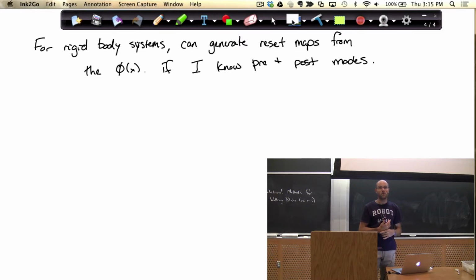But inelastic constraints we end up having to solve with optimization. The closed chains, it's using the same math. You have a kinematic constraint. You have some force that's being applied at the joints to keep that constraint active. But in the case of a closed kinematic chain, you can solve it away. So if you're interested, there's a simple 4-bar example sitting in your Drake folder that shows you how that works in our tool.